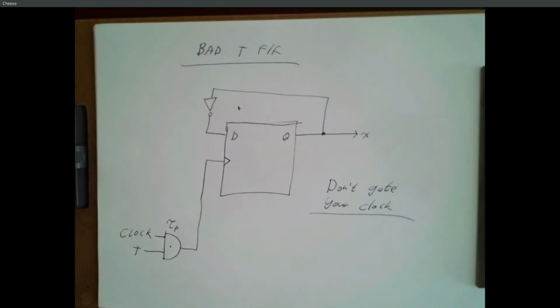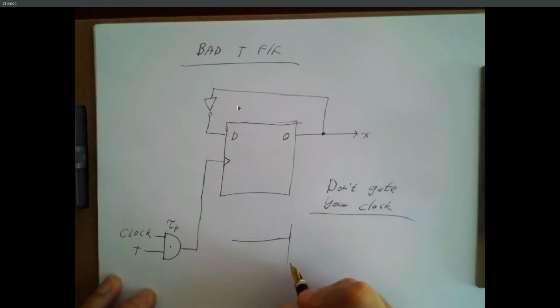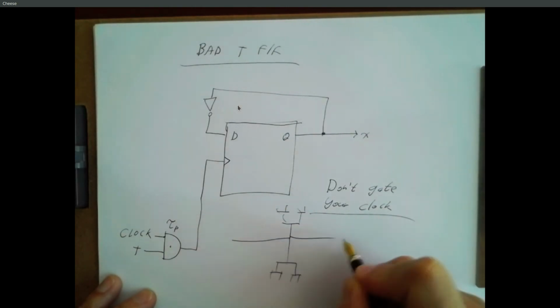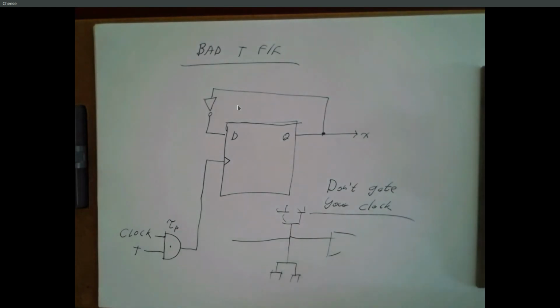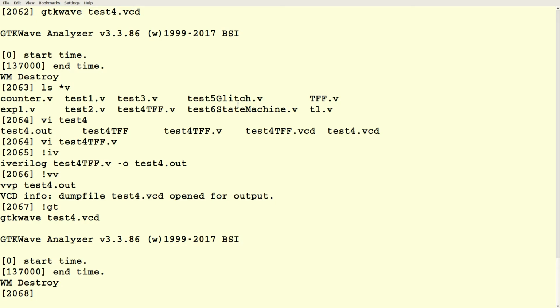But it was serpentine in these Greco-Roman patterns where it farms out into all of these little fractal type areas, to try to get it from your input to the chip to all the different elements in roughly the same path length, to minimize what we call clock skew. So design of good clocking systems is another one of these amazing areas of computer architecture that you can spend a career on.